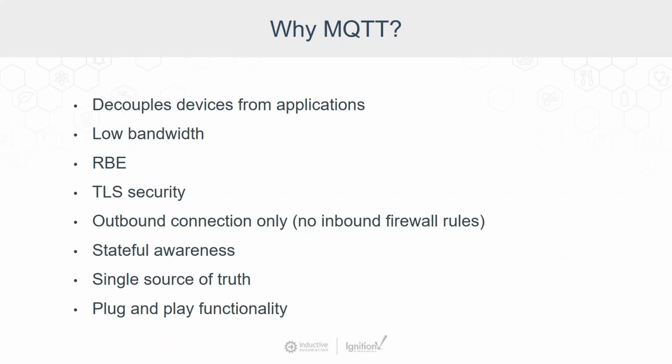This is probably one of the most important things, because if we're in a SCADA system, we have to know that we can trust the values that are on the screens, that we know the quality, we know the state of the connection to that PLC all the way through. And while the protocol decouples everything, the applications and the devices understand this connection, understand this state, and guarantee that we know what's going on.